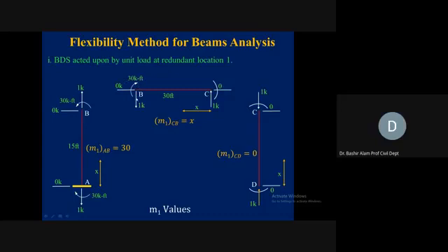Now, joint B has to be in equilibrium, so 1 kip in the downward direction, so 1 kip in the upward direction. 0 horizontal, so 0 horizontal, 30 clockwise, 30 kip counterclockwise, so joint B is in equilibrium. We need to keep this AB member in equilibrium now, so 1 kip in the upward direction, so 1 kip in the downward direction at A. Horizontal is 0. 30 is counterclockwise, so 30 clockwise here at joint B. So joint B is also analyzed and is in equilibrium.